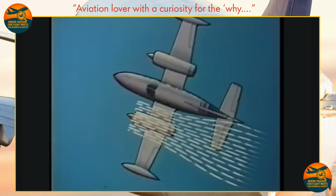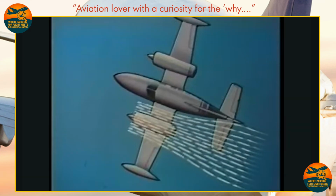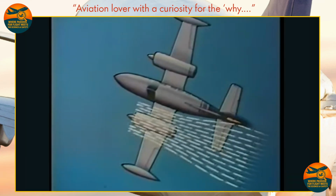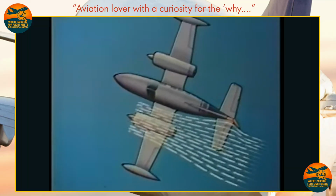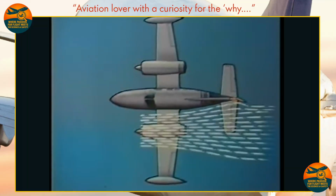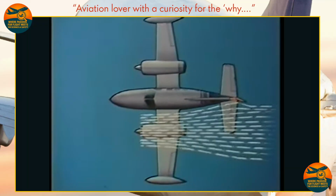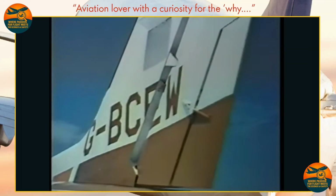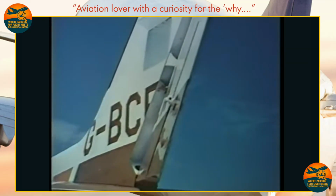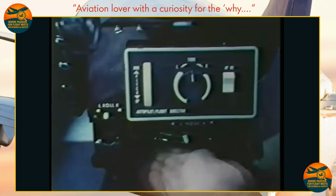To straighten up the aeroplane and restore lift to the affected wing, the pilot must apply rudder against the good engine and hold it there until he can make a safe landing. To do this, he needs help. The way in which a displaced control surface can be held in position against a considerable aerodynamic force is by means of trim tabs.